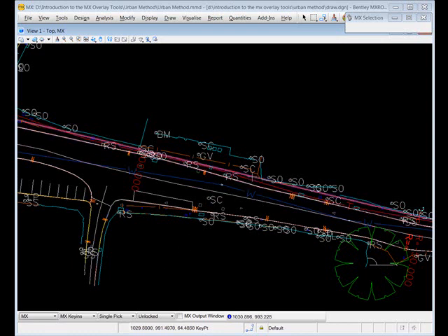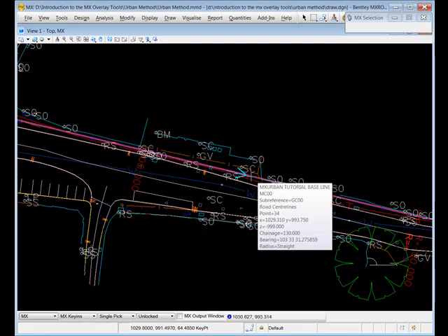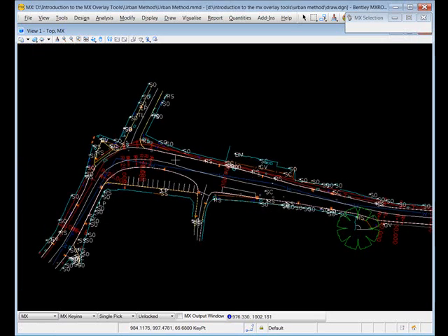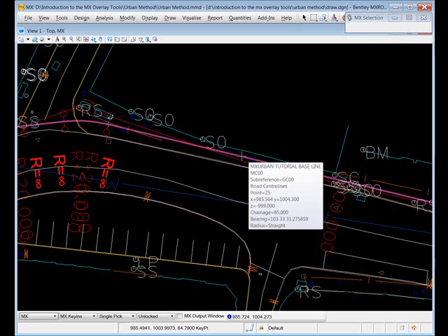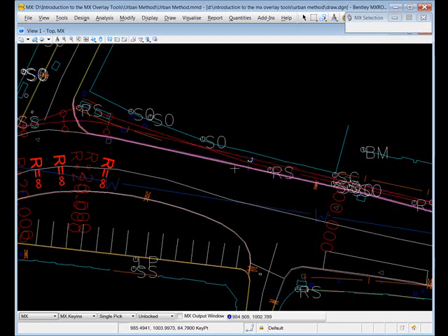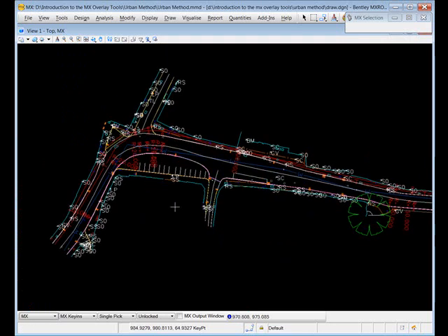In this example, I've designed a new centre line remote from the surveyed road because I want it to be clear of any planing or scarification works that go on within the road surface. So I'm going to use this centre line as a baseline for the design, although it doesn't affect the levels that I'm going to design for my overlay scheme.